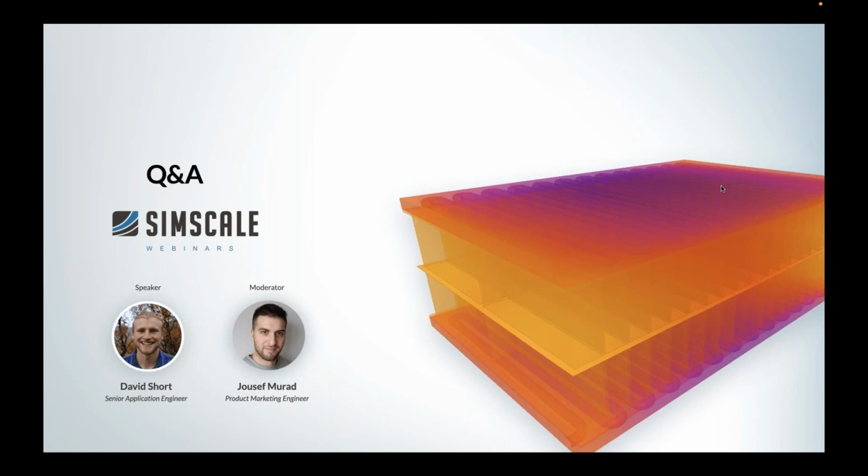So in terms of the mesh elements that we provide on SimScale, we provide first order and second order tetrahedral elements. We use a really robust mesher, which starts off as a triangular surface-based mesh, making it really handy at capturing complex geometry, and then it will build tetrahedral elements out from that triangular surface-based mesh. So it makes it pretty robust, and it makes automatic meshing pretty much all that we need to do.